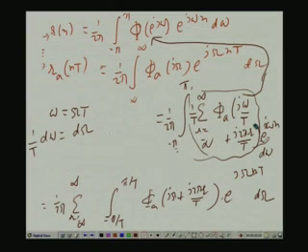Now, I will give a physical interpretation of this, and you will see that by the Nyquist condition you can avoid aliasing. Therefore, you can get the analog power spectral density directly from the digital power spectral density of the sequence, which you obtain by sampling the analog random function. Okay. If your purpose is to estimate the power spectral density of an analog signal, it is better you sample it above the Nyquist rate so there is no aliasing, and find out by some sophisticated computer algorithm the power spectral density of the corresponding sequence x n. Okay. From that, you can easily construct phi a j omega. So, I will start from here in the next class. Thank you very much.